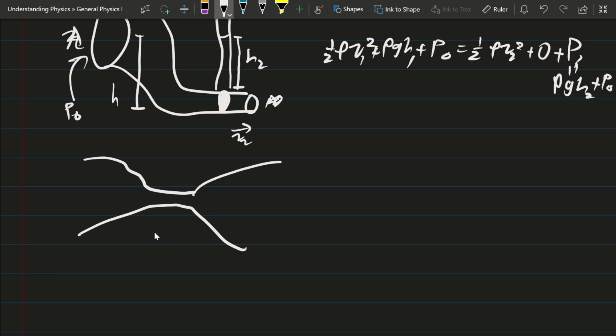in which there's a constriction, and sometimes you put some form of fluids in here, so you could measure the velocity, thanks to knowing the pressure gradient as well as the area. So with that, you could figure out what the velocity of the fluid is, and you could get your mass flow rate, for example. So that's one of the uses of a Venturi.